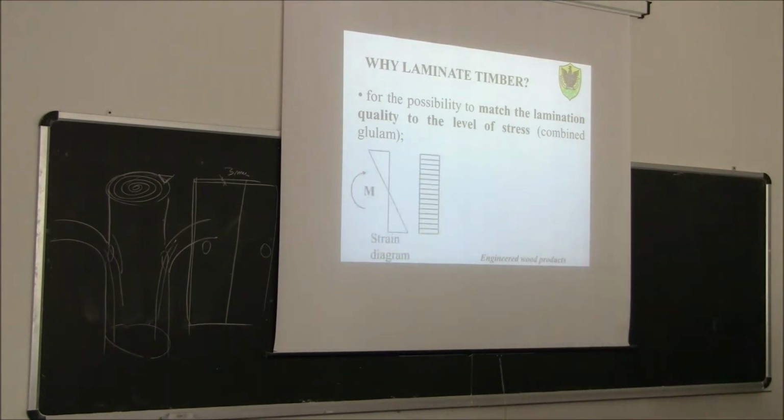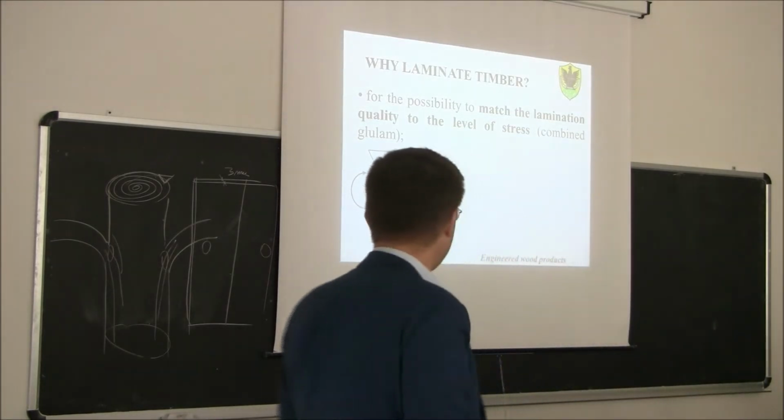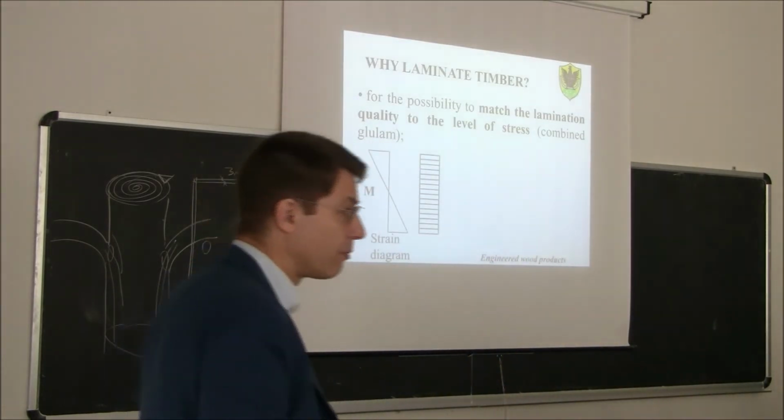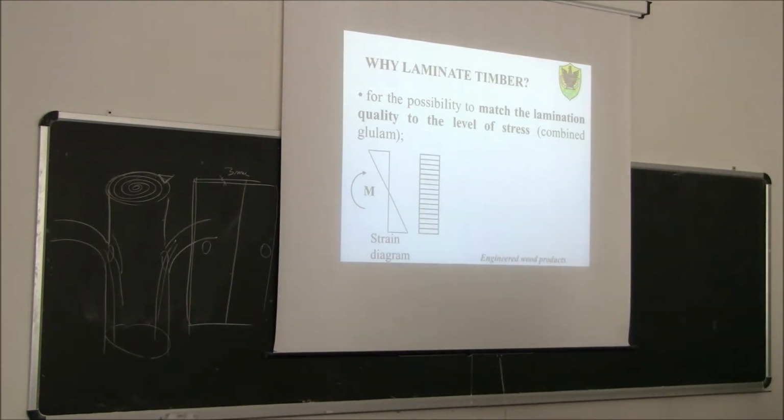Well, the idea is that, of course, when we create a straight member, very often we use it for a beam. And for a beam, we know quite well that, if you remember, we said that conventionally we will design a timber member for bending, assuming a conventional linear distribution in tension and in compression.